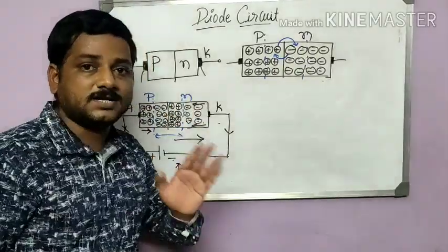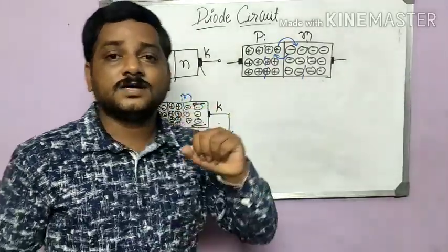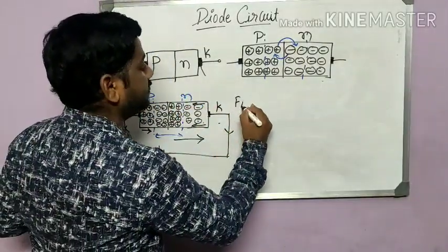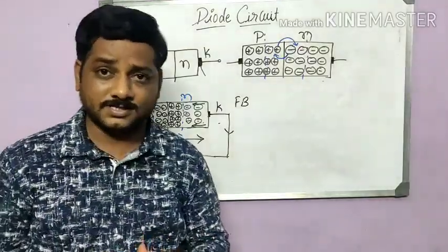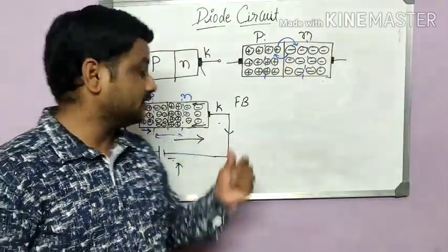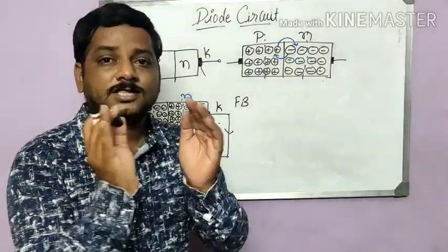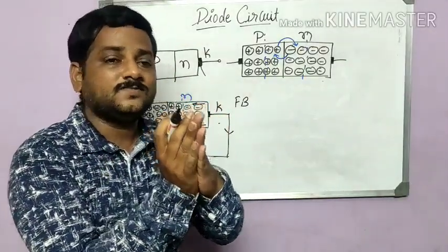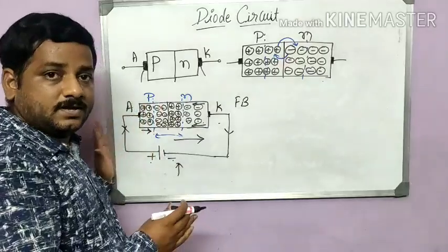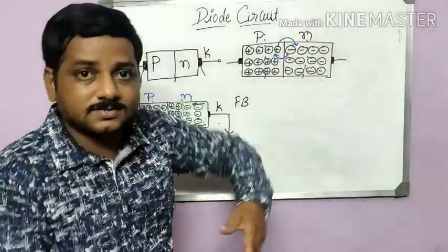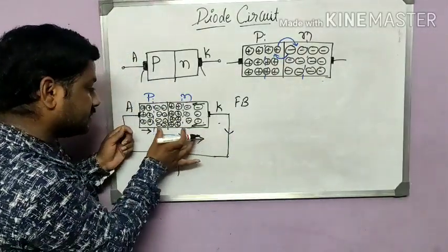This is the conventional current direction. So this is how it works in the forward bias. We name it as a forward bias. So in forward bias, what actually happens over there? We are narrowing the space charge region, okay, and we are just allowing the electrons to flow, and the conventional current will be taken like this. Okay, so it is just rippling and it is narrowing.